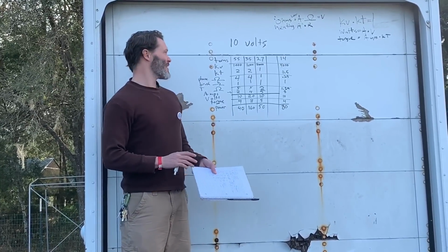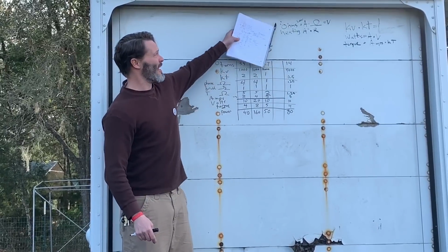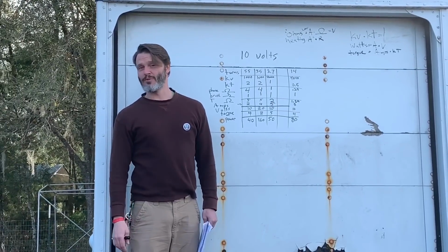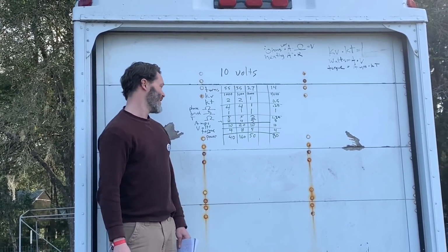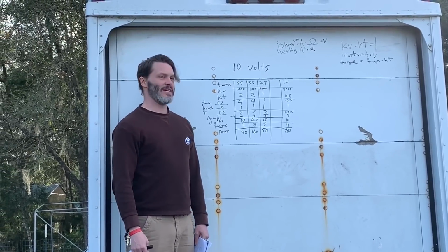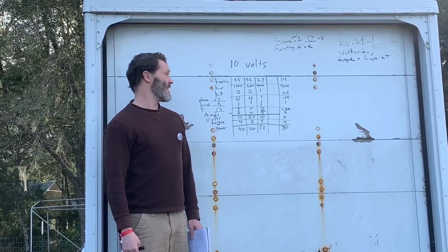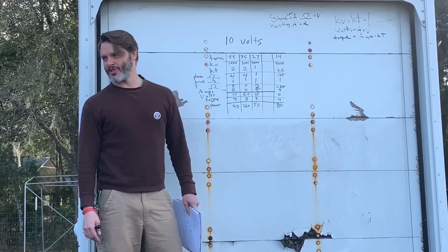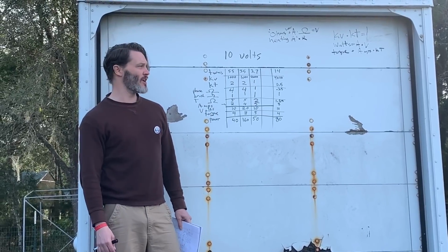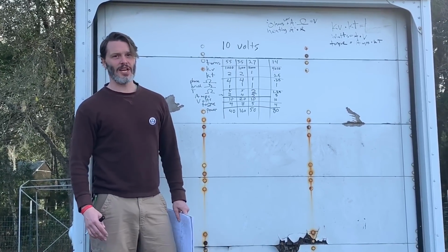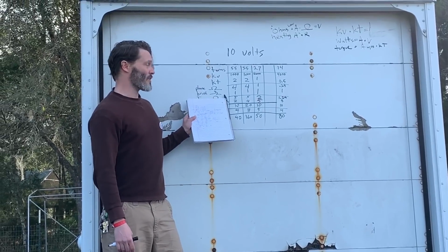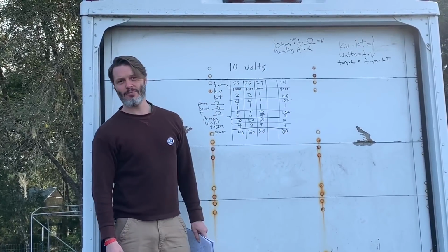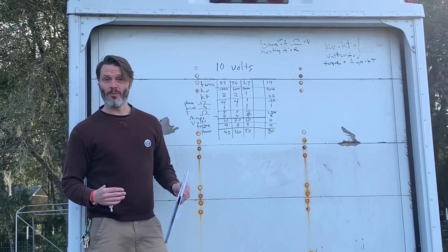Now, I don't know if I can really get into it easily, but the next thing that we would look at at this point is the heating losses. And the heating losses are always going to be your problem in the system when you're working against it, trying to get more torque out of it. Heat's the bad side of electronics. And in most cases, now we're looking at the slow motors, the heat's actually going to be the same until you start saturating your brushes or saturating the coils in the motor. It's going to work out the same, because as we go up 4 times in phase resistance, we actually have heating that is the square of the amperage. And so it actually balances out to where a motor is a motor is a motor.